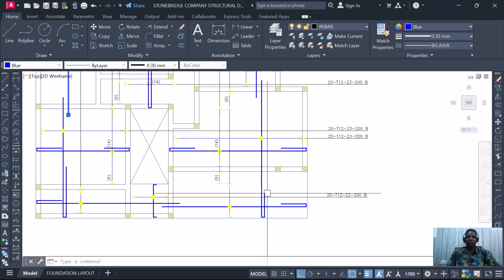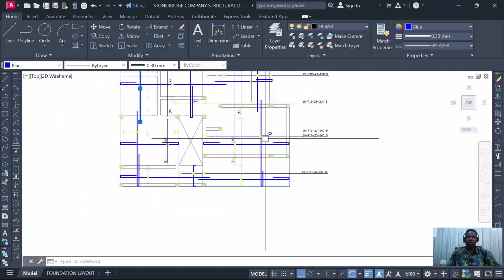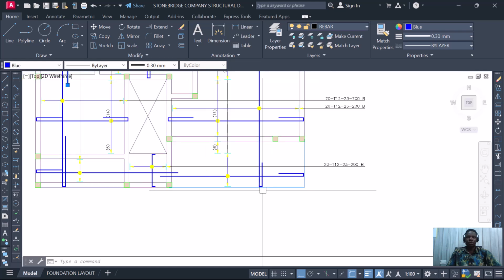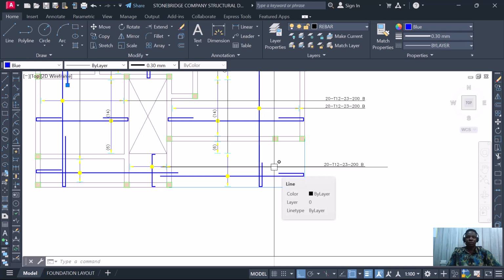Before we go, we're going to look at the cantilever slab. If you look at what we have here on the cantilever section, a lot of people detail it this way, or they'll begin to introduce a top rebar along this area. So when you're designing the cantilever slab, what you need to do is take a particular mat. After matting it, you get to the edge.